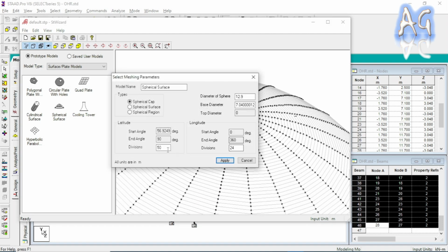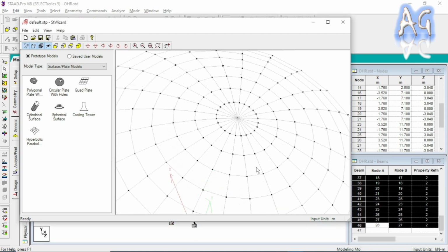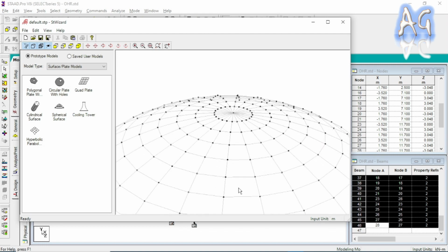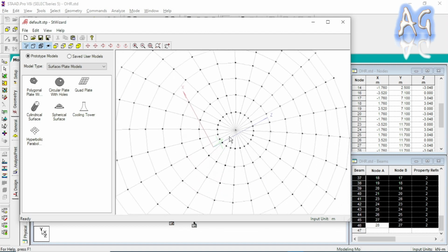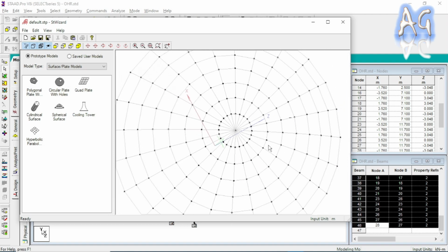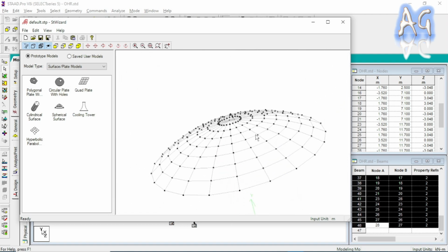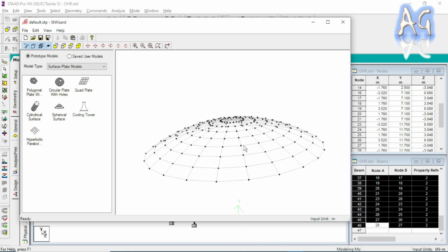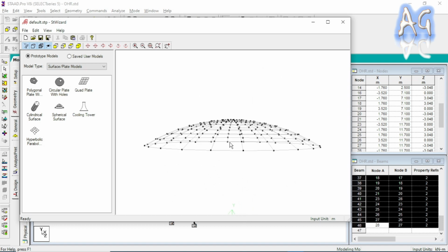So what you will do is provide a value so that all the plate shapes are a square, or near equal to a square plate size. So I'm just going to provide 8 here, so that you can see the plate size is almost okay, and here also the plate size is almost okay. That is very important when you are adding elements or members in your model.